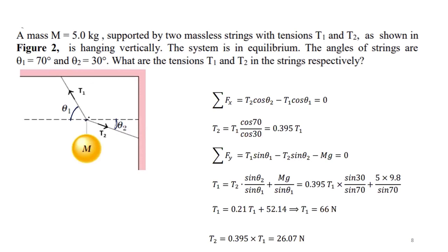So I'll choose this as my origin, this as my positive x-axis, this as my positive y-axis. And I will say that the balance of forces is equal to 0 because this point is at equilibrium. But here I will have this tension 3, and tension 3 in magnitude is just equal to the mass of this object, mg. So if I do the balance of forces, I will have an equilibrium problem: T1 plus T2 in vectors, plus mg, is equal to 0.